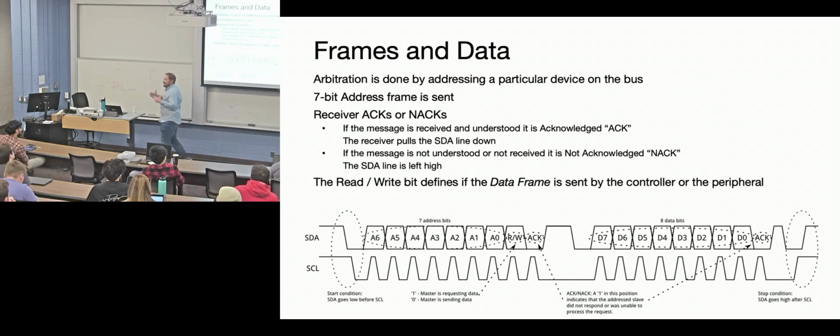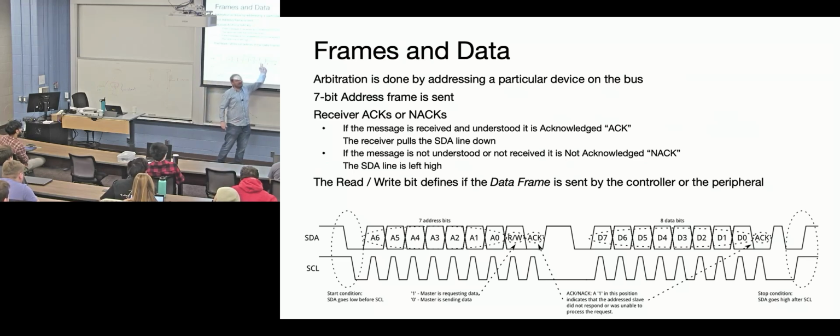And so one of the common mistakes is that you're trying to write to some peripheral, and it's always NACKing. NACK meaning no acknowledgement, ACK meaning acknowledgement. What is the error condition that can occur if you're always getting a NACK? A NACK is when this bit is high. Try to take 30 seconds, think about what happens if you're trying to keep talking to a device and you're never getting a response from it, and how that might manifest here.